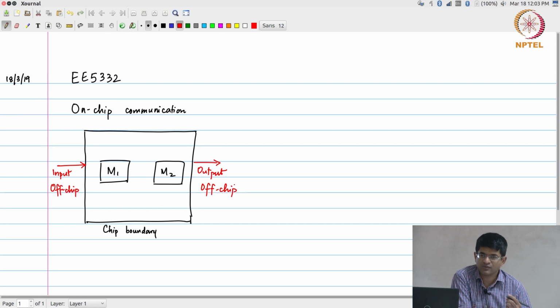It is not very clear why you would study the on chip versus off chip things separately, except for one specific characteristic. Typically, the moment that you go off chip, outside a particular chip, it means that you are leaving the silicon wafer, you are going over metal wires, going out over a PCB trace, going into another chip over its bonding pads and so on. The capacitances that are involved over there are typically a few orders of magnitude higher than what you would have inside a single chip.